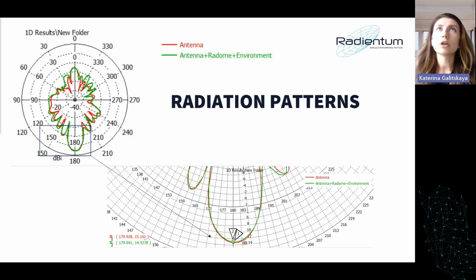In the beginning with the shark fin antenna, we also had a radome, but at 900 megahertz you just need to know the dielectric qualities of the material and then the size, and that's all. You don't need to worry so much about that. But on millimeter waves, it affects the antenna a lot.